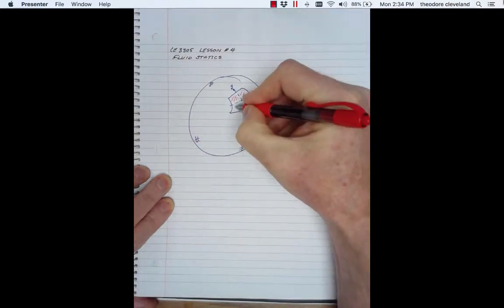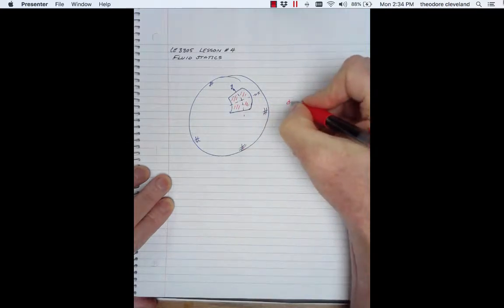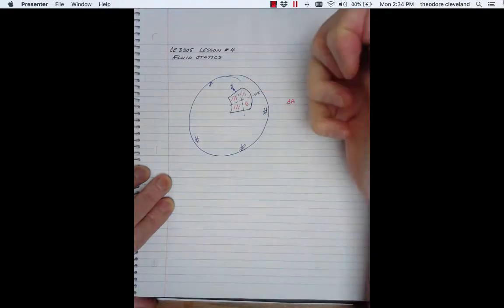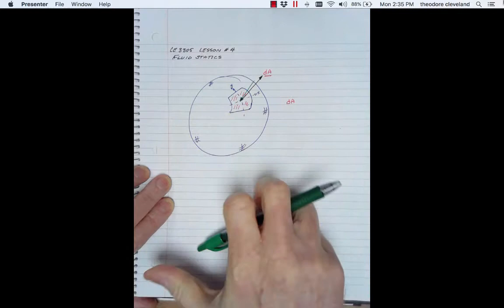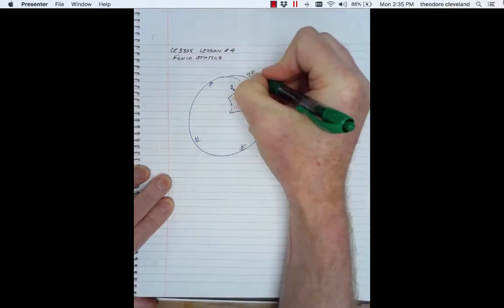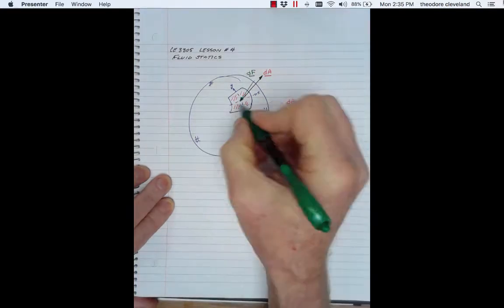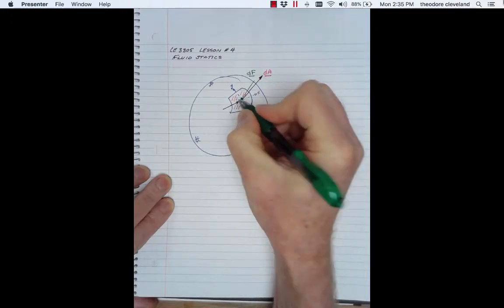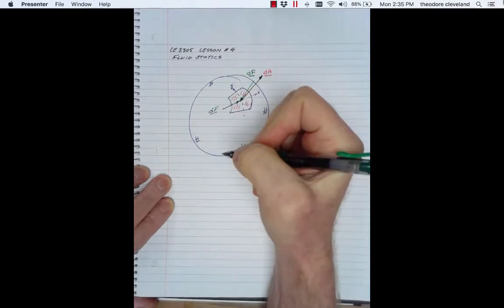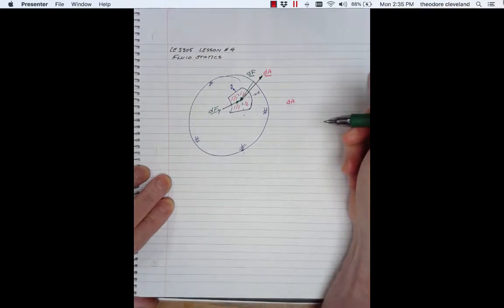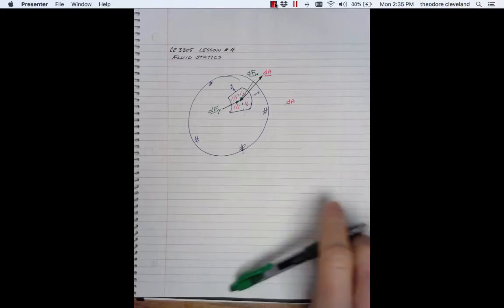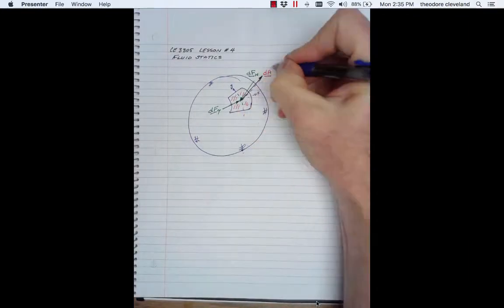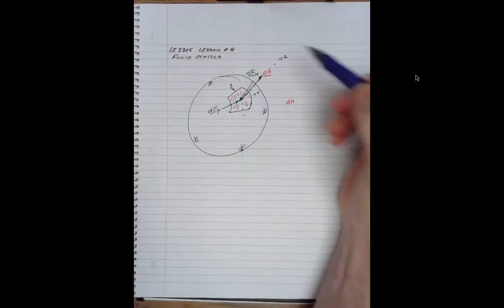This entire area has magnitude dA, and in vector notation there'd be some outward pointing vector associated with it, the dA vector. That hand that we were pressing on it with earlier would be the dF vector, where F corresponds to a force. And if this bubble had some sort of tangential force applied to it, we'll call that the dF vector, and that's now going to be given the subscript tau to imply that that's a shear force, and this will give the subscript n to imply it's a normal force, and we'll eventually start calling it pressure. The third axis, which I didn't draw initially, is here. It's the z-axis.